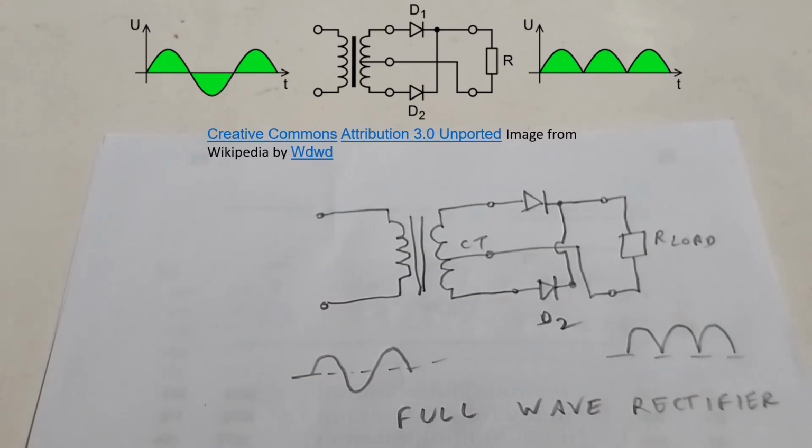If you connect the output of a half wave rectifier into a loudspeaker, you will have a ripple sound with 50 Hz frequency. That is the output current of a half wave rectifier. If you connect it to an oscilloscope, you can see the pattern there as I have shown in the drawing.